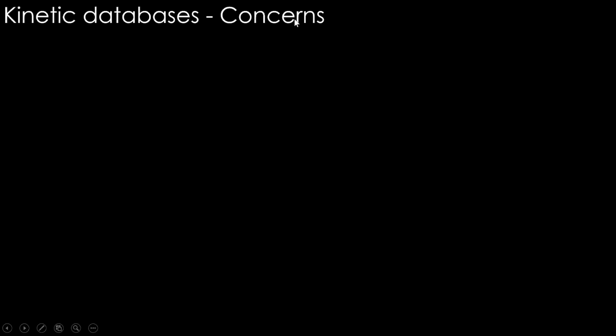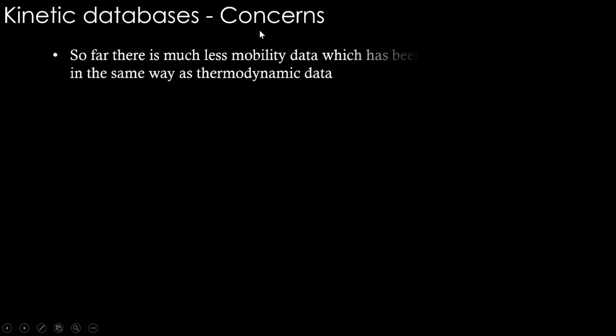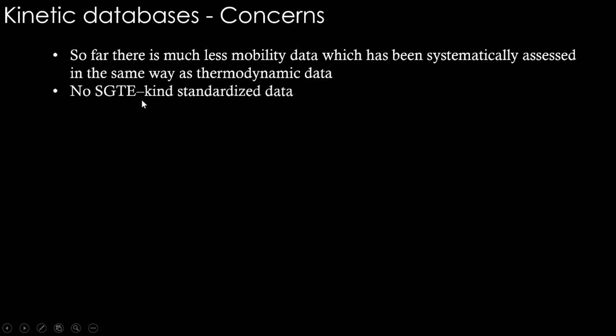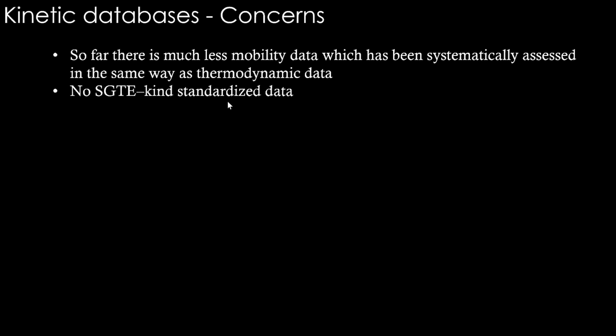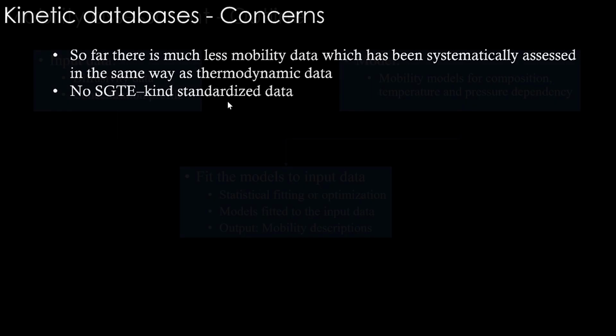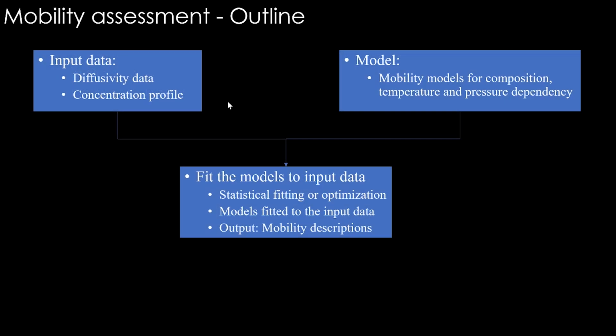So there are a couple of big concerns with this kinetic database, which I am going to list now. So far there is much less mobility data which has been systematically assessed like the thermodynamic data. So not a large number of systems are assessed for mobility. That is one big problem. The second big problem is there is no SGTE kind of standardized data. Even for a unary element, one element diffusing in the same environment, there is no standard data available. Therefore, mobility assessment has to be done.